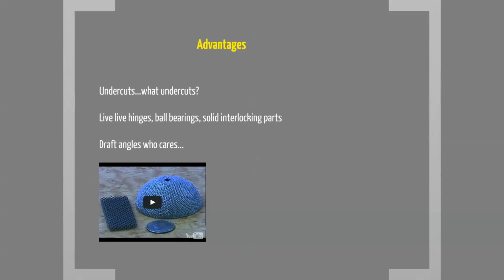So if we look at different advantages, the advantage of 3D printing is that it doesn't require you to be as conscious when you're designing. Now, I say that lightly because I don't want you guys to just think, oh, now that we're 3D printing anything, you don't have to think about how you make things. Well, no, that's not the case, because 3D printing is still very expensive, so you have to be careful as far as material and all the other stuff that you have to incorporate when it comes to a design. But undercuts, what undercuts, right? Because you really don't have to worry about undercuts, because everything is being laid up layer by layer.